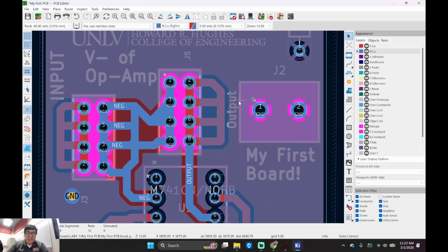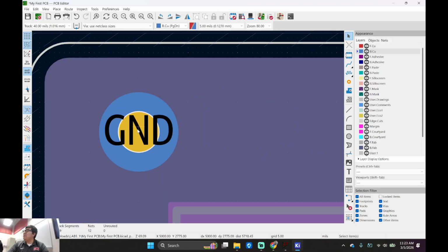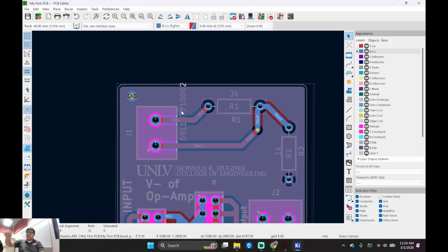So else, this student's board, if I look at it, he has the ground vias, right? Do you guys know how to do the ground plane? You guys are understanding why I'm doing a ground plane? Because they're gonna give you a piece of copper, top copper, bottom copper. It's gonna be an empty piece of copper, right? And they're gonna etch it with like a little knife, right? The reason why we put this copper here is so they only etch out.